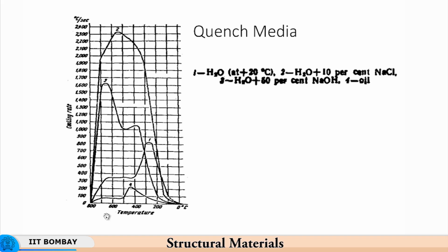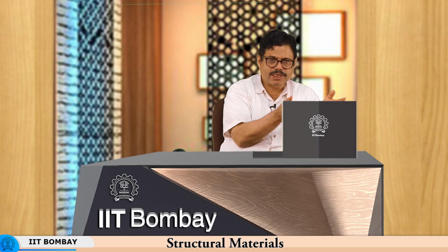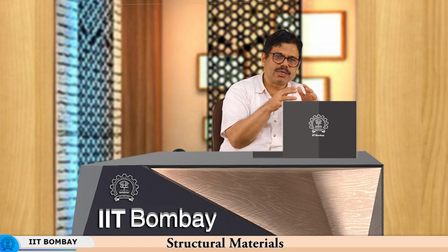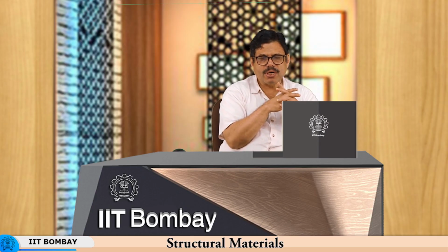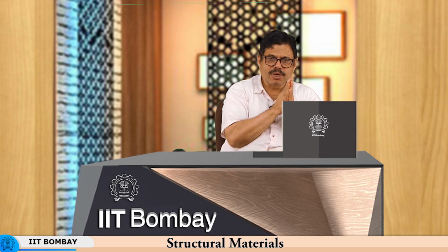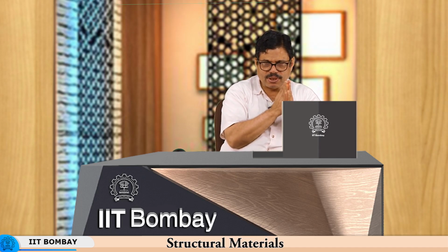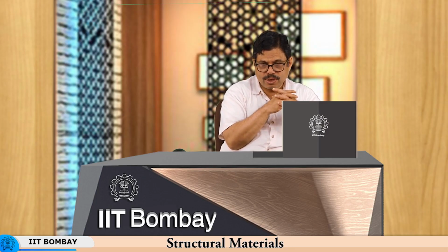prolonged durations. And comparatively, you may want very gentle cooling rates, particularly when you want to cool down at relatively low cooling rates. Again, the same example of high carbon material being heated to a very high temperature, you would not like too high a cooling rate. Oil, by virtue of its chemical composition, will tend to decompose if it is subjected to a very large amount of heat. So, you need to take care that the temperature of oil does not rise too much and the oil does not decompose.